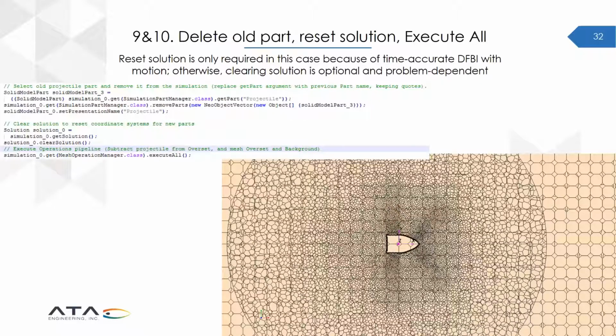So you're not having to compute all of these different properties and store it in a giant spreadsheet or a giant table or array or structure ahead of your for loop. You can actually get this from STAR and then dynamically update it using the Java scripting that's available within STAR-CCM+.